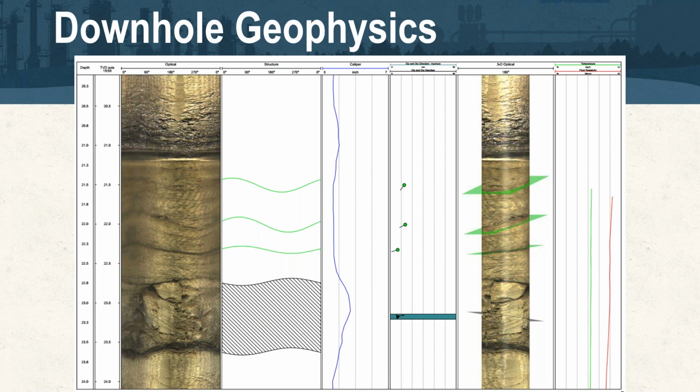What we always advise, or stress, when we do coring versus setting the characterization points, is that the core location is independent from the other characterization points. What we found from experience is that if you do a core location and then try to over drill or ream that core location out, even the best efforts of a very skilled drilling contractor can have some level of deflection from that original path.